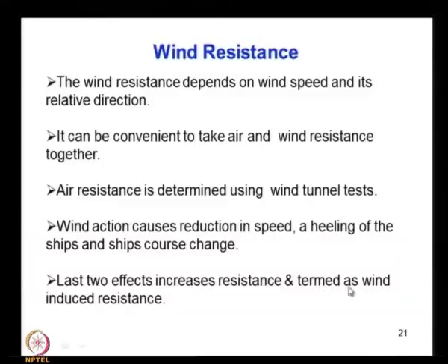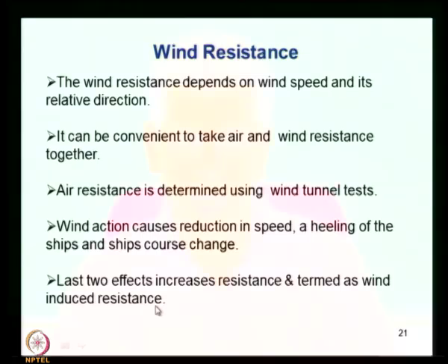The last two effects, that is the heeling and course change, increase resistance and are termed wind induced resistance. Actually, it is not the wind directly blocking the ship; because of the action of the wind, the orientation of the ship changes and subsequently the resistance increases, then the speed comes down. That is why it is called wind induced resistance.